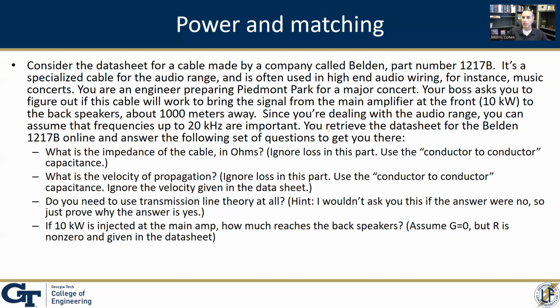First of all, what's the impedance of the cable? What's the velocity of propagation? Do we need transmission line theory here? And then what kind of power can we expect to reach the back speakers? I think that's the important part. If we lose all the power before it gets to the back speakers, obviously we better find another cable or come up with some other solution, maybe put a repeater in the way. So that's the idea here.